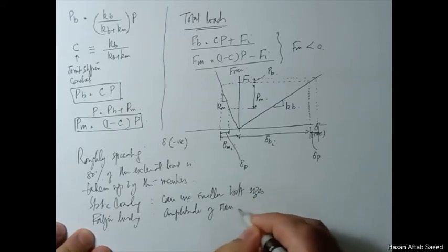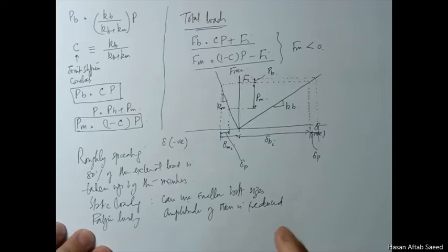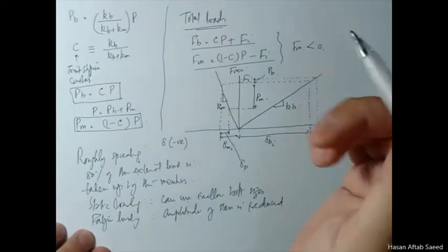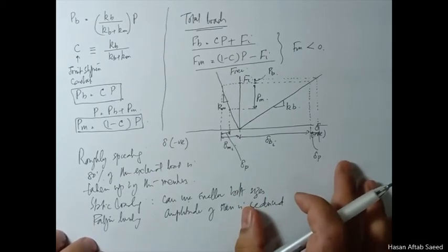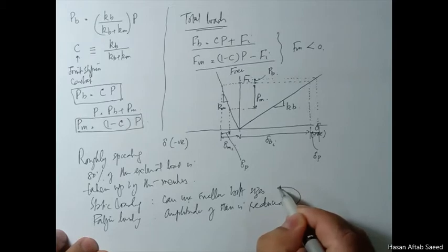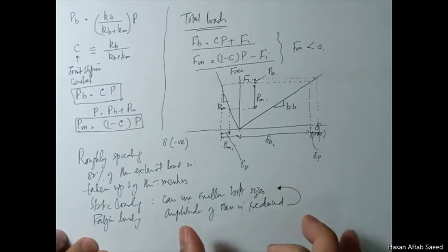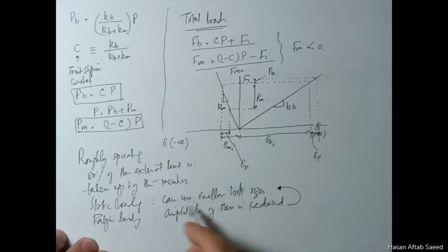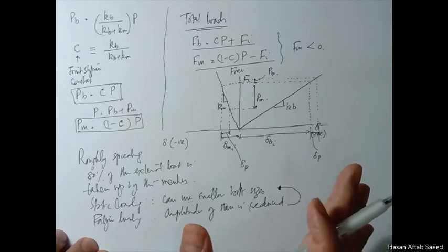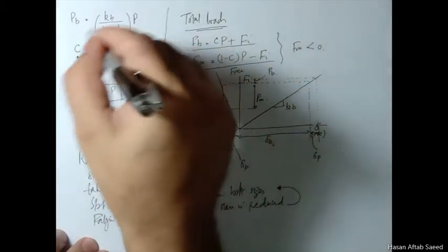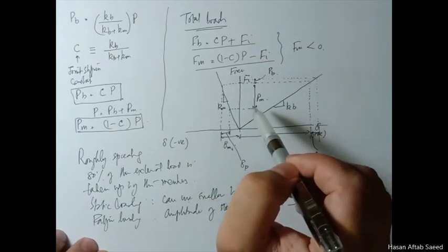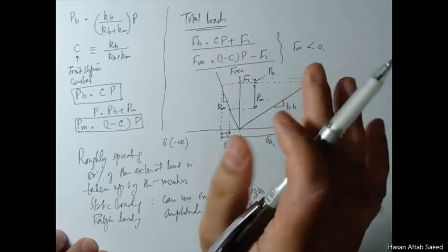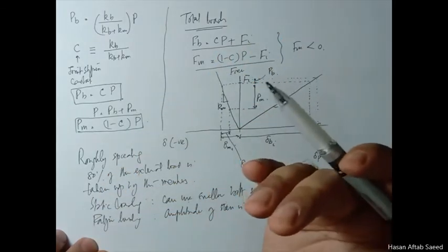stress is reduced. So the fatigue life increases, and obviously in the long run, if you see the bigger picture, this also translates into this: because if the amplitude is reduced, then you can use a bolt of a smaller size to withstand the same fatigue situation. Otherwise, if most of the load was taken up by the bolt and not the members, then you would have been obliged to use bolts of much larger size.